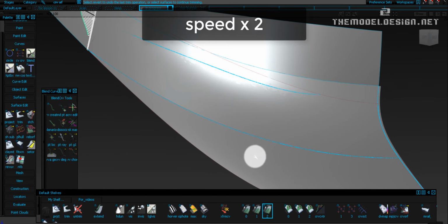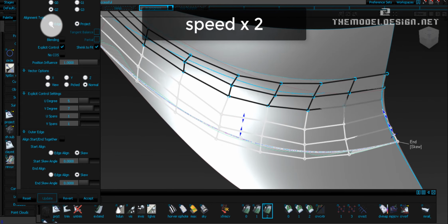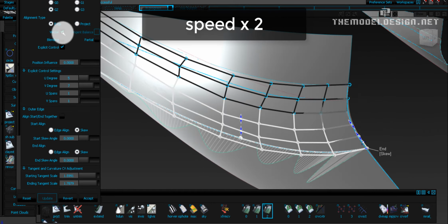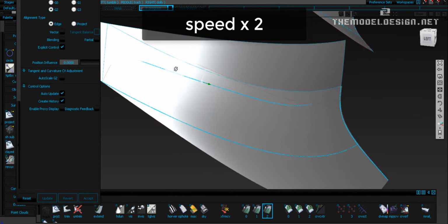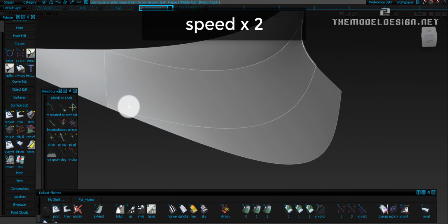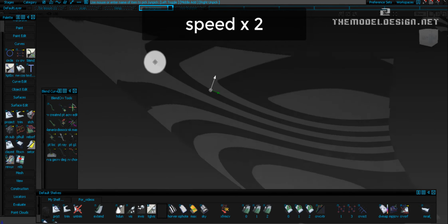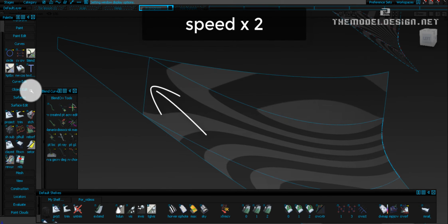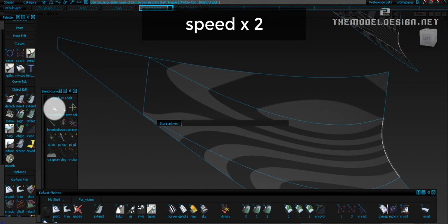Let's do the same with the bottom edge. Let's add some degrees. And finally, examine the zebra stripes. Our zebra stripes look decent. In this area, we still have a continuity problem. Therefore, next we will have to think how to sort it out.